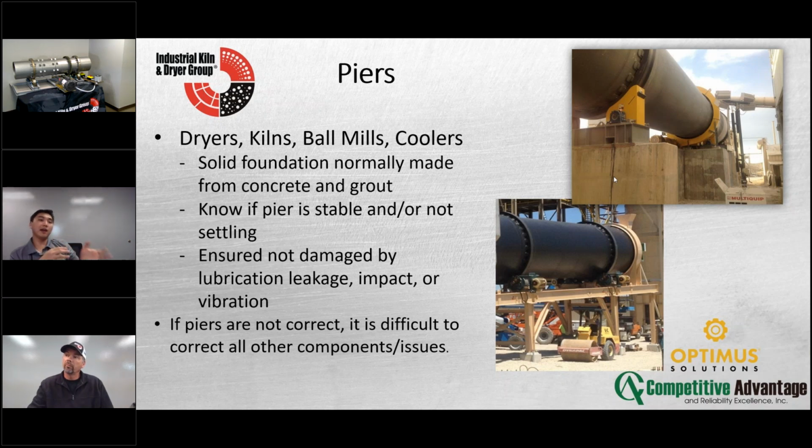That's why you have concrete and rebar: concrete for compression strength, rebar for tensile strength. When you put those two together, it makes a very, very strong composite material. Carbon nanotubes are very strong in the tensile category, and when you add them in, it creates better strength. That's my interpretation of that.